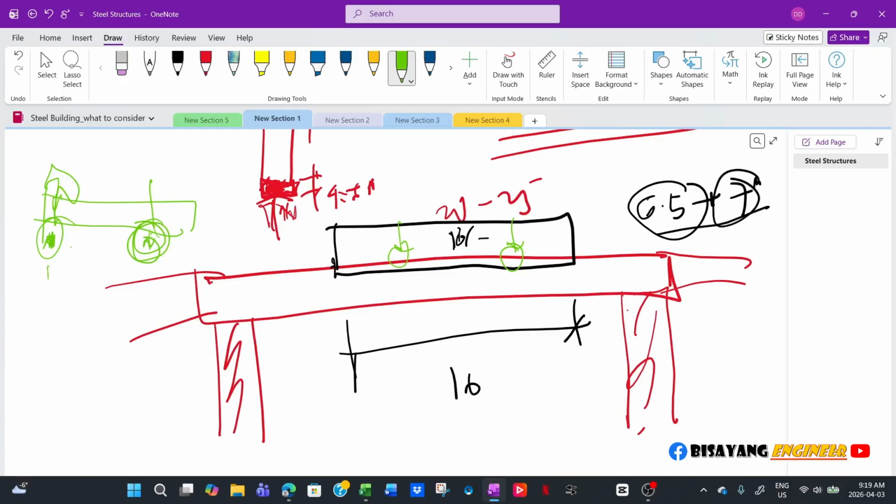So when I design and size the grade beam, I will use the axle load of the rear axle because that's where the heavy loads are. And then in the framing plan or foundation plan, I will clearly indicate that the maximum axle load is say 24,000 pounds. If that's the axle load, half of it will be 12,000 pounds, 12 kips, and this is also 12 kips.